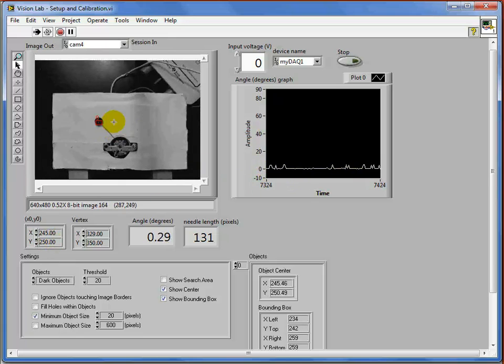There's a little bit of noise fluctuation there. Let's play around with this and see if I can fix that. See, if you fix the threshold a little bit, it seems to be right on the edge. You can almost take that noise away. Maybe we can even go a little bit higher. And now, see, it's sitting a little bit more consistently. And now my 0 is at 246, 245, so I'm going to adjust that.